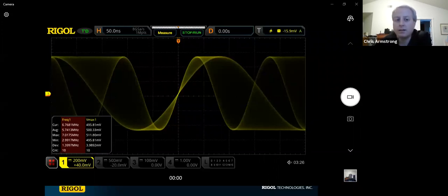So yeah, I agree with that. If you're in the guts of a Raspberry Pi or some embedded technology development, I think the ability to look right at that bus and say, okay, here's the byte order that's coming across is great. So when I program it to send out a little ASCII string to my device on the other side, this is exactly how it's being encoded and transferred. That's a great way to look at those signals and see noise and issues that are arising.